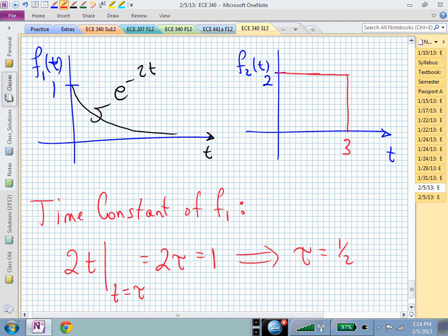That's 2.5 seconds. So we're actually going to reach our steady state before the pulse stops. Is that making sense? So we will have reached our final value effectively before the pulse turns off. So we'll be coming up here and then we'll shut down.